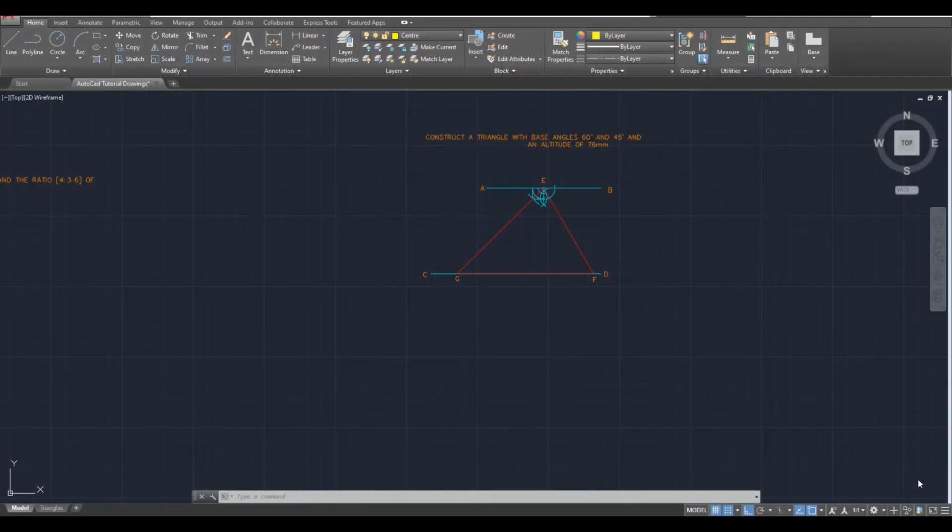Okay, so we're back here in CAD, and now we're looking at the pan tool. The pan tool is a very useful tool in CAD. It may be accessed several different ways, but one of my favorite ways is to type the command P to bring it up. Why? Because sometimes you may be in a dialogue, or maybe you don't have a menu, or the callout menu is displayed, but you know that P on the keyboard brings it up. So that makes it quite easy.